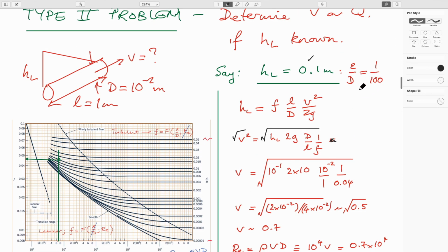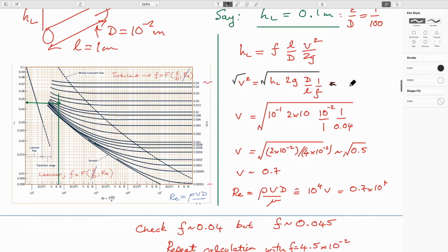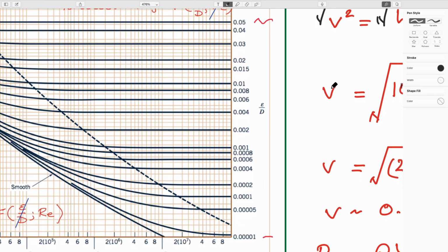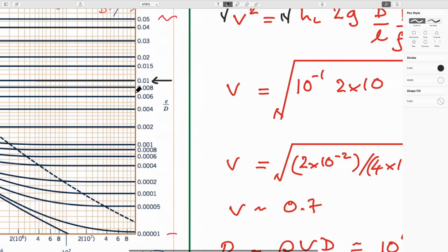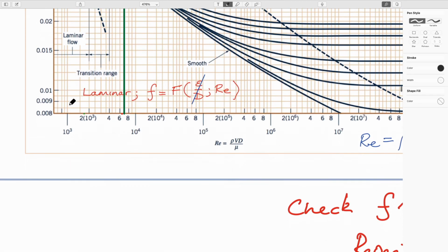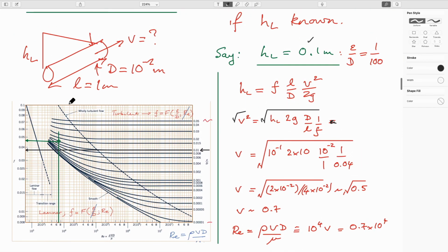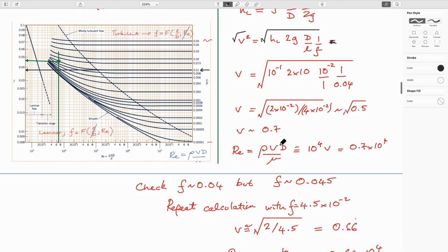So in other words, if you assume it's turbulent and the roughness is equal to 1 over 100, then we know that, I guess I drew this diagram here for a reason. Then we know, if you're told that the roughness is this, and this is the value, so you're somewhere along here, then I think you're there, so you're 0.03246, 0.038. I can't remember what I used, might have just used 0.04, because that's roughly the same, makes life easier. And if you do that, you can almost do that by hand.